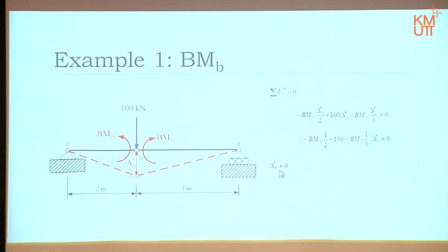Arguably, delta B is not 0, small but not 0. Therefore, what is inside here must be 0. There we are. Only one unknown here, and therefore we can calculate the bending moment straight away. If we trace the calculation, we should find that this bending moment is positive.